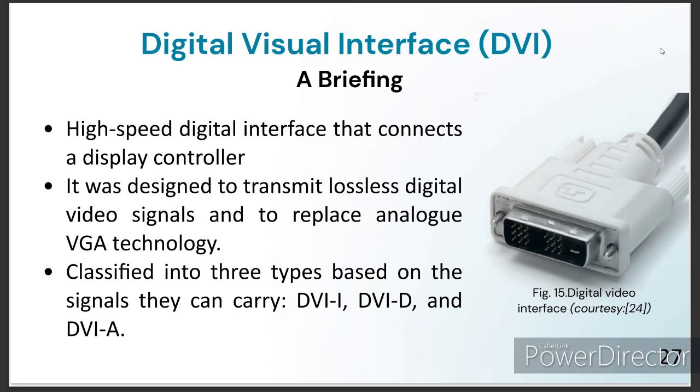Digital visual interface. High-speed digital interface that connects a display controller. It was designed to transmit lossless digital video signals and to replace analog VGA technology. Classified into three types based on the signals they can carry: DVI-I, DVI-D, and DVI-A.